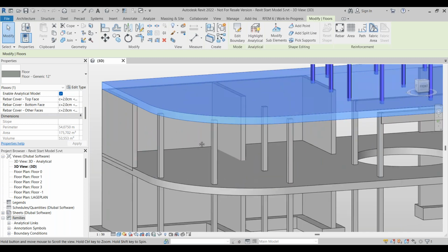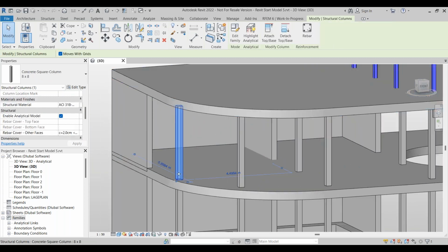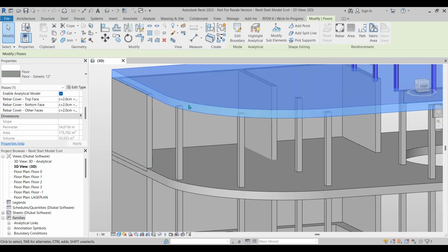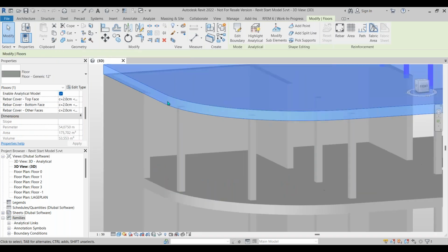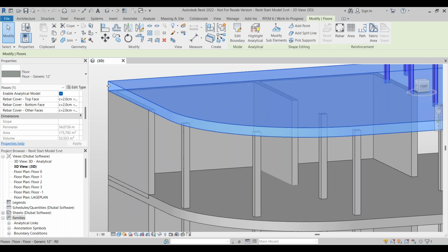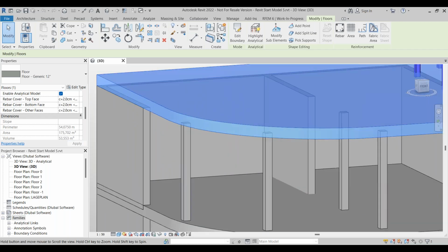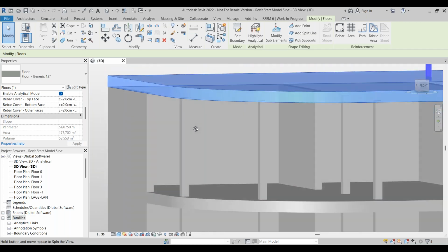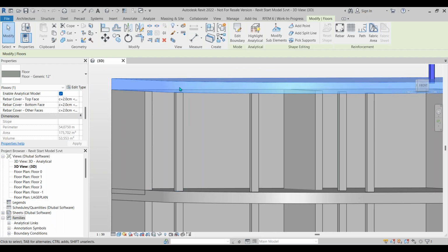And so if I'm converting my column, for example, into a simple center line that goes up the center of gravity of the column, and then a 2D object for my slab here, which is going to go at the halfway point of the thickness, then naturally I'm going to have a gap that is going to appear between these two lines. And so what Revit is also doing is not only converting these objects into surfaces and lines, it's also connecting this gap afterwards.